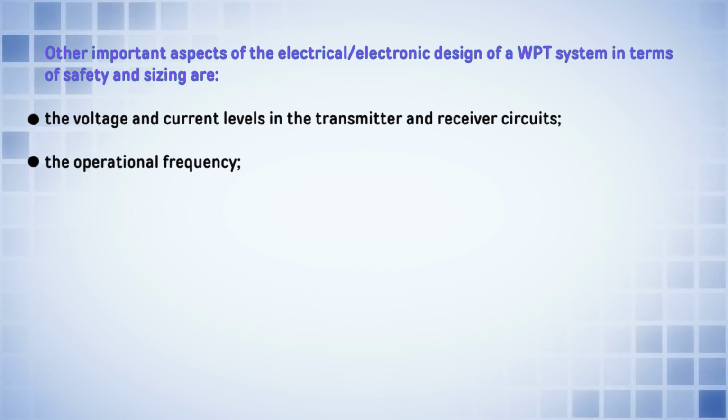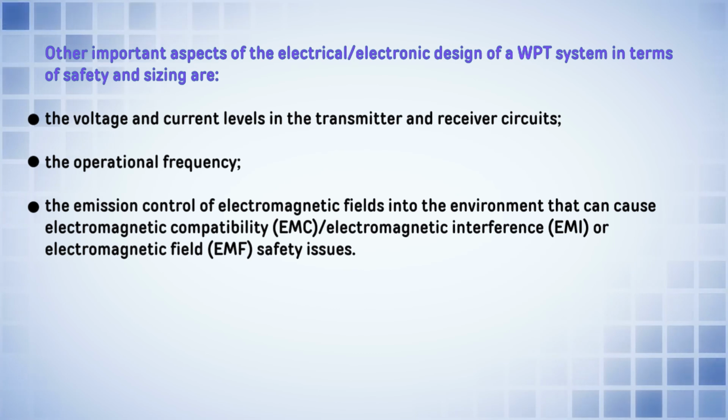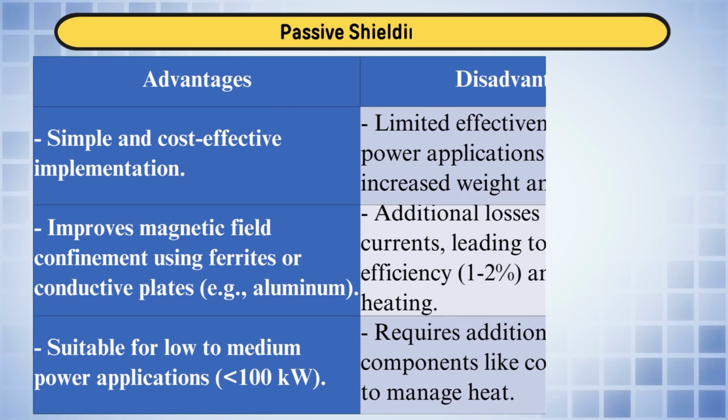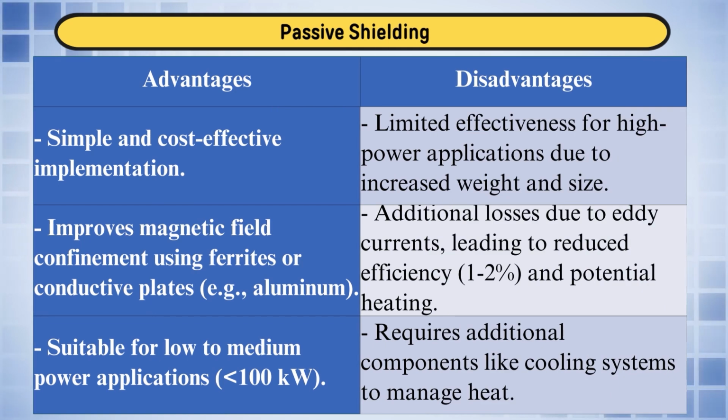What are the challenges in EV charging? One is efficiency. We have to increase the efficiency of these DC-DC converters. We have to switch these devices at very high switching frequency, so that the converter size and transformer size can be reduced. Thermal management is also one of the challenges in EV charging. Heat dissipation must be proper. Battery life: avoiding overheating and ensuring long life of the battery through precise control, so that we do not inject any kind of ripple into the battery which may degrade its life.